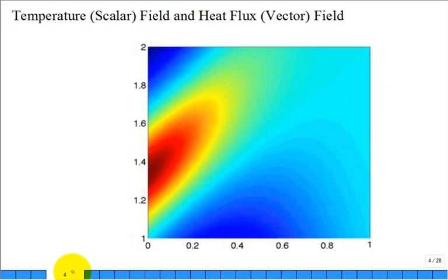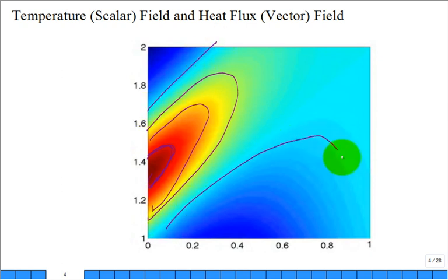A lot of times you'll have thermal contours. They'll color code. Maybe the blue is cold, the red is hot. And then maybe you come in here and you would be able to sketch a line of constant temperature. That would be an isotherm. That would be a different isotherm. Maybe this is a different isotherm. Maybe this isotherm kind of goes like that, in our domain. So if you wanted to visually represent the temperature field, you use color graphics like this, and maybe you draw lines in 2D or 3D.